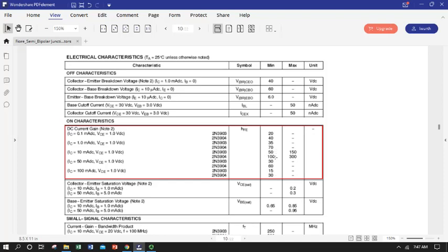And so when you see something in a problem or some kind of project description where you're asked to calculate something about a transistor circuit where you're given a beta, chances are it's going to be that beta under ideal operating conditions. It's going to be this maximum beta. And even for a given collector current, check out the range. This is one transistor, one temperature, one collector current. You could have a beta that really floats anywhere between 50 and 150. Wow, that's a big change in gain.